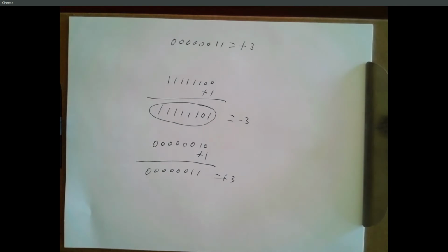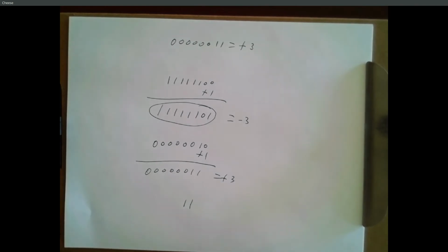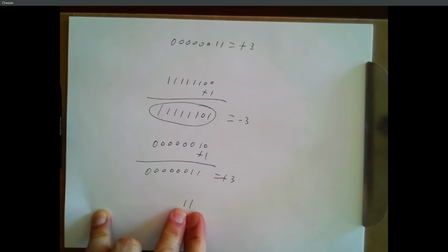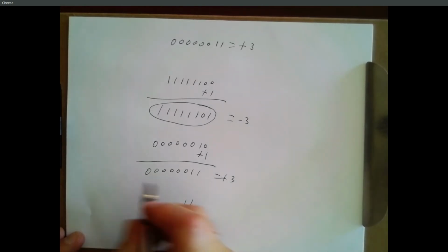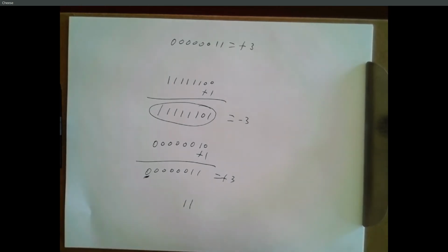And when we write positive numbers, if we want to write the number 3, we don't write 0, 0, 0, right? We usually just write down that. But if we don't know how many bits we're talking about, we don't know if this is positive 3 or negative something, right? It's only if we write out all these bits and we see this leading bit is a 0, now we know this is a positive number. So if it's an 8-bit question, just make sure you do all 8 bits, even if it's just a bunch of zeros, right? Because they'll turn into ones when you do this complementing.